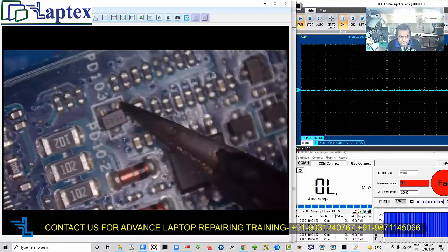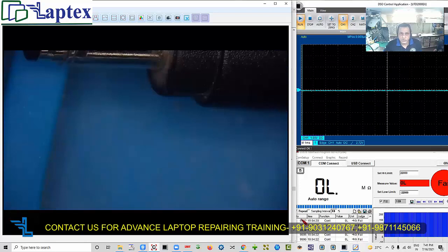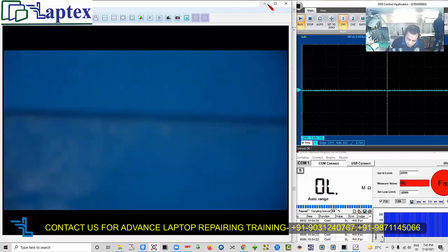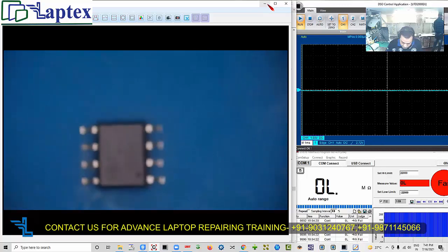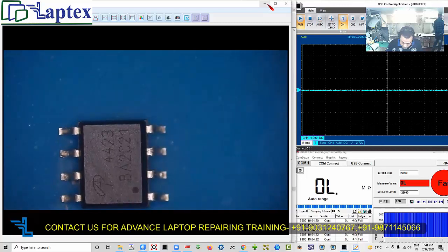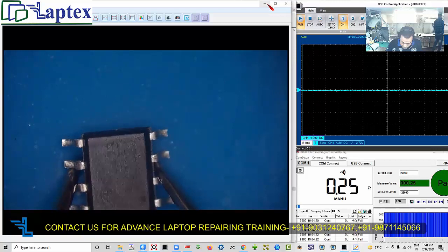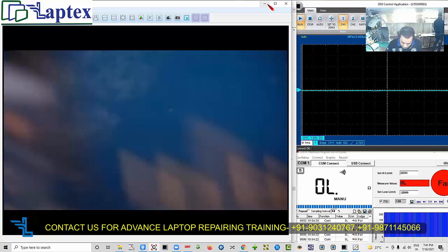Now you can see PD103, when I removed it and injected the DC jack into the board, it got massive shorting, and this is the MOSFET. This is the MOSFET which is shorted from drain to source. Now let me show you how it is shorted. It is on the beep. Now you will see, it became 0. So now I will not make such a mistake.